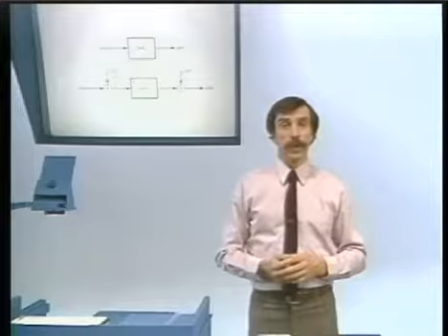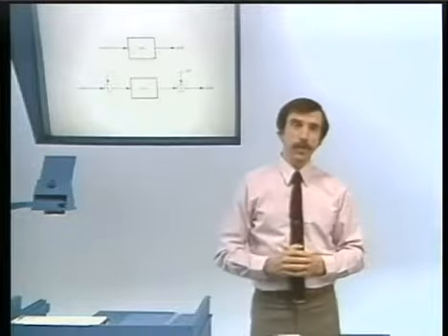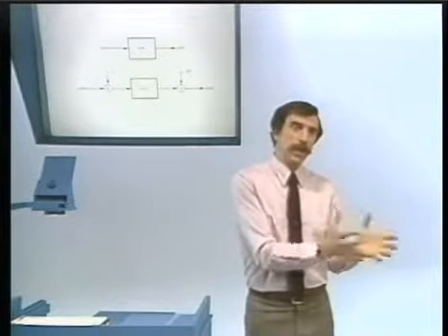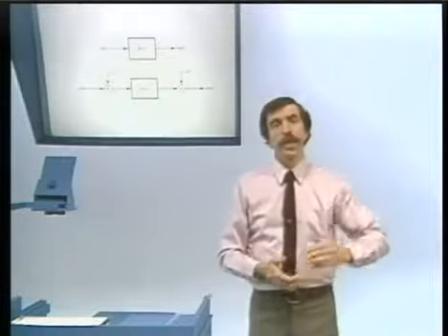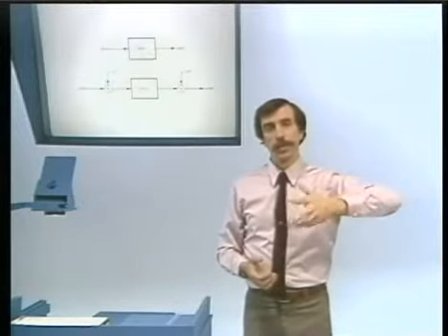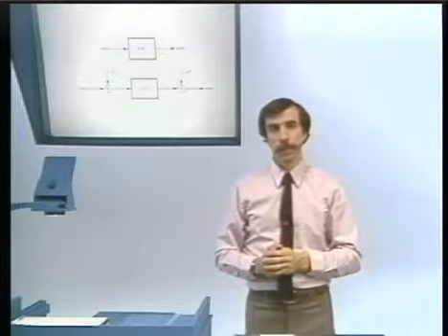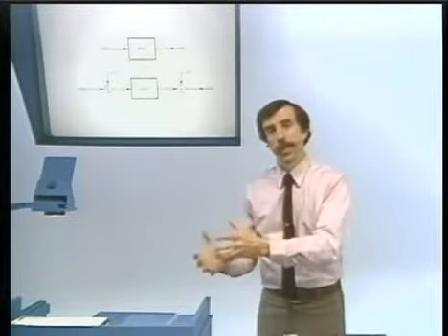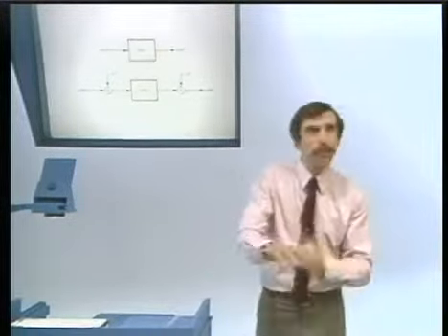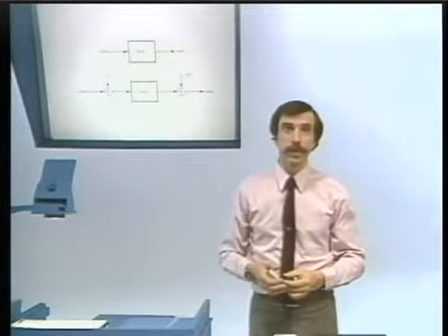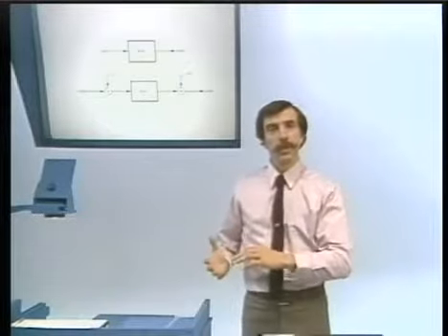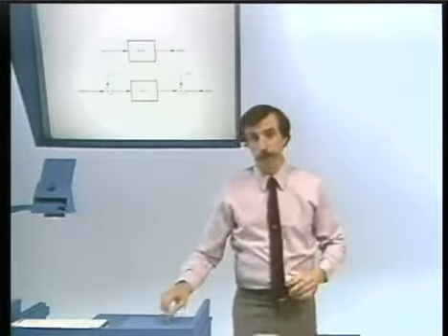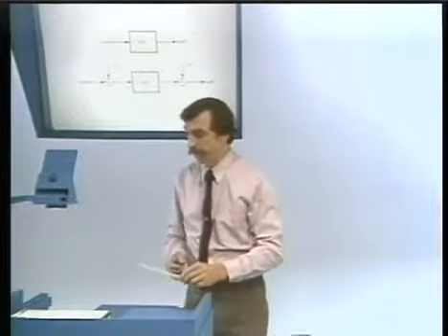Well, one way to do it, instead of shifting its frequency response, is to take the original signal, shift its low frequencies to high frequencies and its high frequencies to low frequencies by multiplying the input signal by -1 to the n, process that with the low-pass filter, where now it's sitting at the low frequencies where the high frequencies were, and then unscramble it all at the output so that we put the frequencies back where they belong. And I summarize that here.